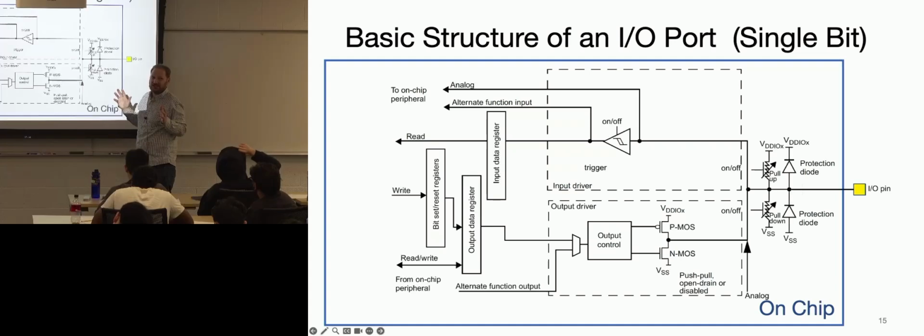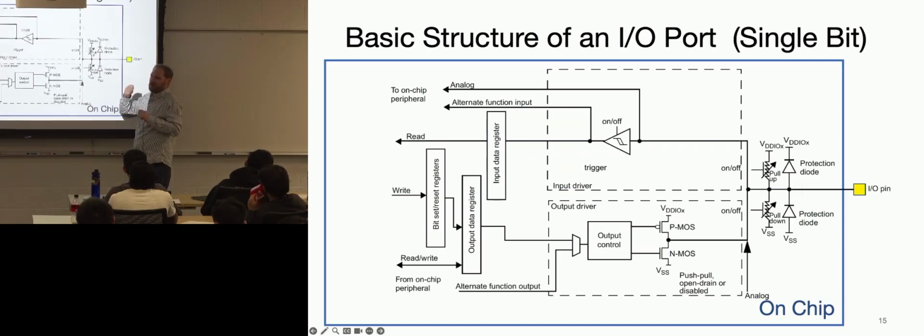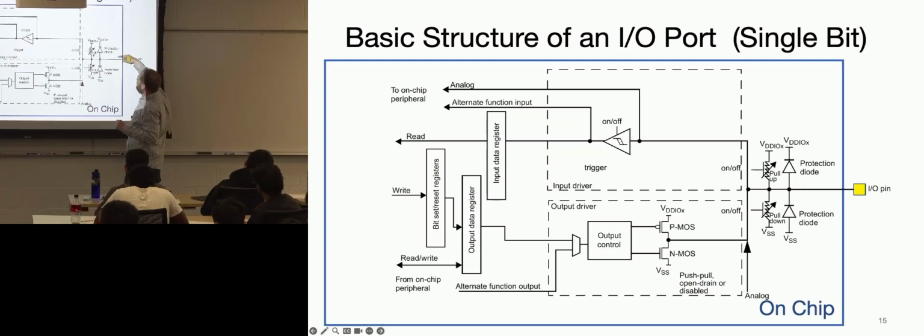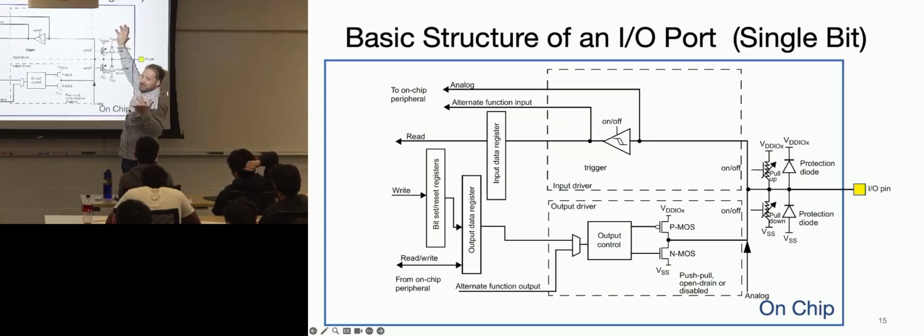So I actually had an error condition in one research project where I was doing some weird energy harvesting, and all of a sudden the clock would go wild. The clock would start increasing and going faster and faster on my little tiny microcontroller. I couldn't figure out why. Well, this was back in the day when little microcontrollers weren't quite as good as they are now, and they had voltage-dependent internal clocks. So they had a ring oscillator that would ring around, and when my little energy harvester went into some weird state I hadn't considered, it was actually pushing voltage through this pin up here, raising the VDD of the entire chip, and then changing my clock frequency. And, you know, it only took 2 weeks of my life to figure that out. It was pretty cool.